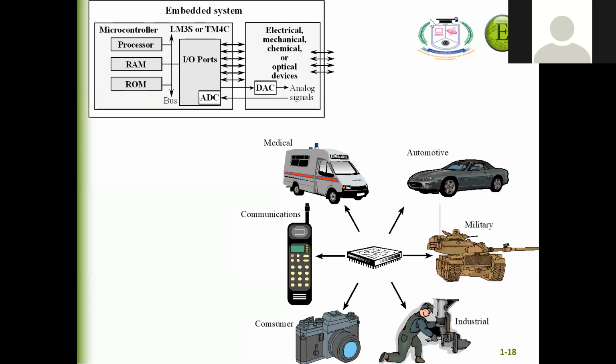And bit handling instructions are fewer in a microprocessor. In a microcontroller, there are many types, many bit handling instructions. Very good, wonderful. Actually, bit handling, I told you: SETB is to set the bit, CLR is to clear the bit. So if I want to switch on and off, I can use this simple instruction, not only in one port, I can do it with all the ports.